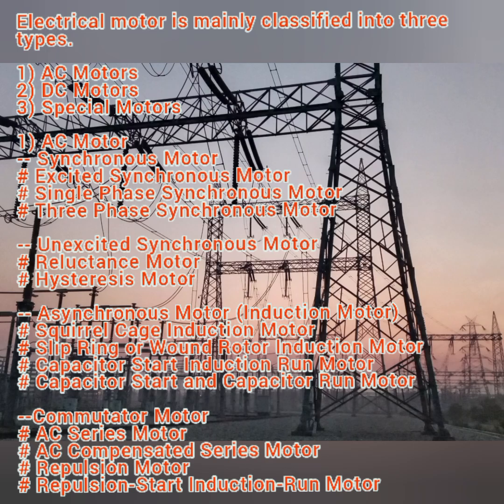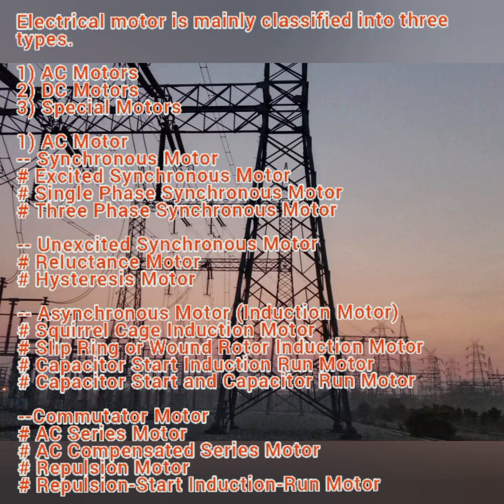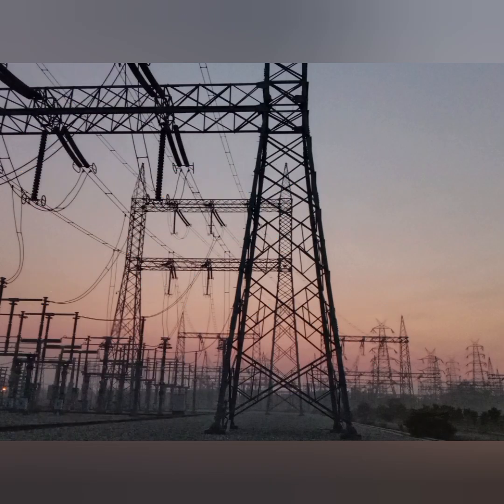Then asynchronous motors are the induction type of motors. They are further subdivided into squirrel cage induction motor, slip ring or wound rotor induction motor, capacitor start induction motor, and capacitor run and capacitor start induction motors. Then the commutator motors are subdivided into AC series motor, AC compensated motor, repulsion motor, and repulsion start induction run motors. So this is all the main classification of AC motors.